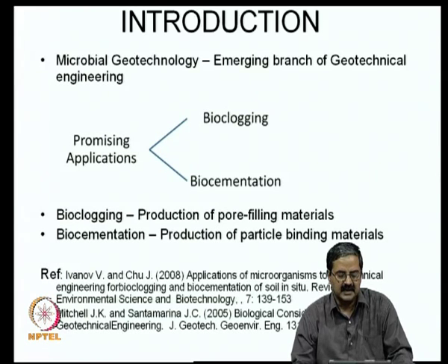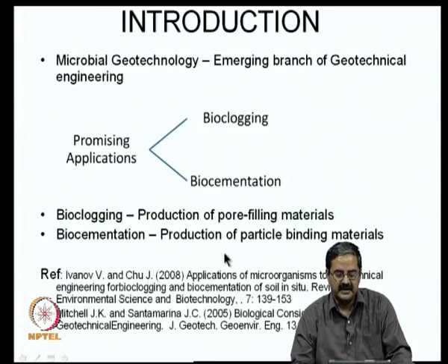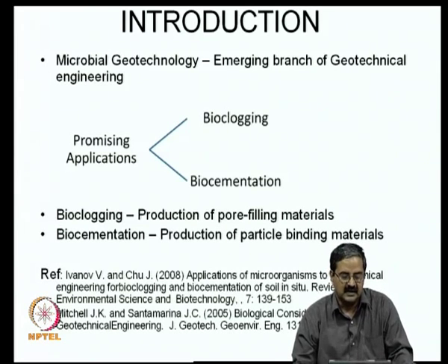The second thing, similarly, is that you are trying to introduce cementation. Normally we use cement in the case of some materials to introduce cementation in the form of bonds, but if you are able to get the same cementation effect using some sort of bacteria, then it is going to be very nice. So, you are trying to introduce these concepts of bioclogging and biocementation, which we can say are more sustainable technologies, because bacteria are always available in nature, and at the same time you are able to have a good advantage of these materials.